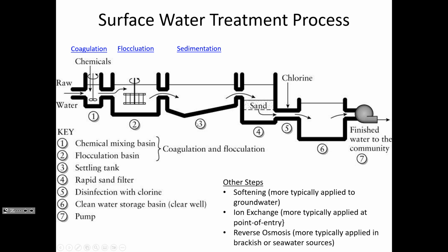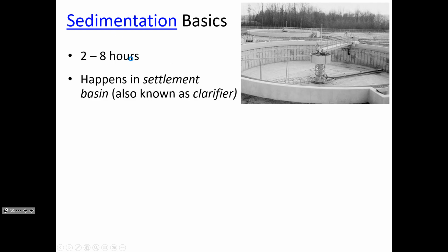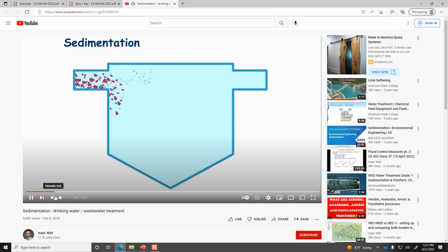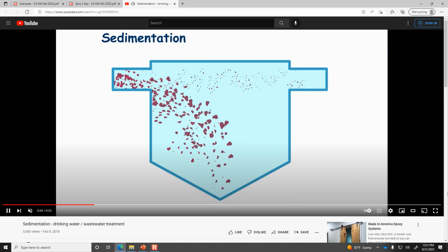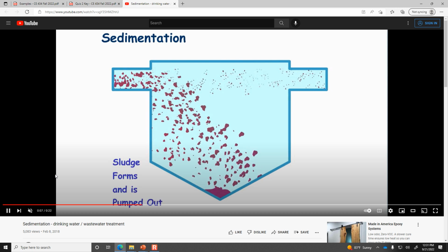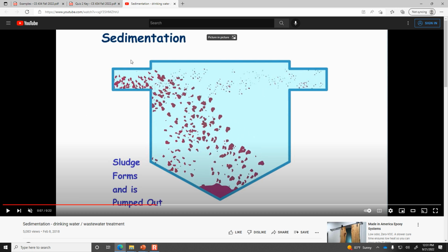And so what we're talking about today is the sedimentation step. And just to review this little conceptual animation, that's intense. All right, so we have these large particles which have formed through the decreasing intensity of flocculation. We have maybe multiple chambers where we're reducing the mixing energy, and the floc particles have grown larger, and then we just need some quiescent tank for them to settle to the bottom,